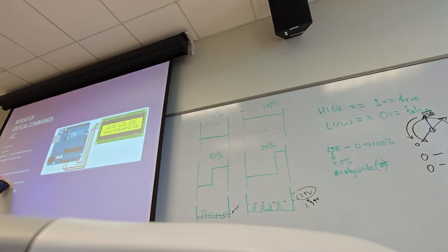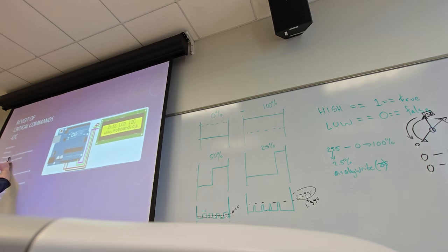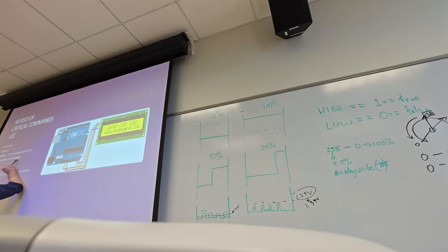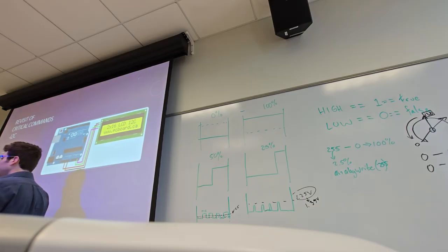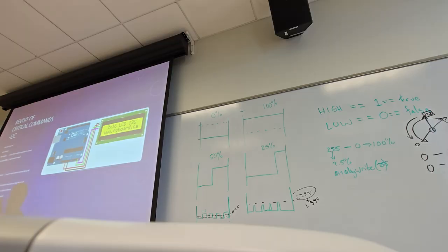Inside of our setup function, the one that only runs once, is our begin call, where we join the bus. Again, there's lots of things that this does behind the scenes that tidies up and connects to the bus and starts communicating on it. Same with our serial bus. This is talking to our debug menu on our computer. The human readable, this is the current temperature, this is the pressure over time, that we tell ourselves when we say print lines, okay? So that is that interface, and here's our loop.